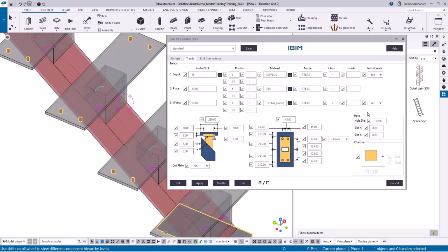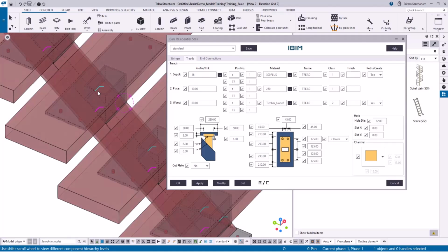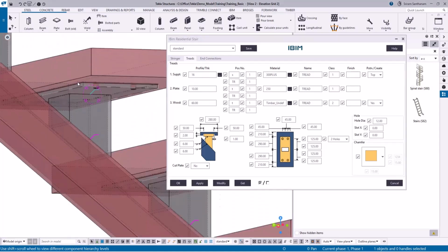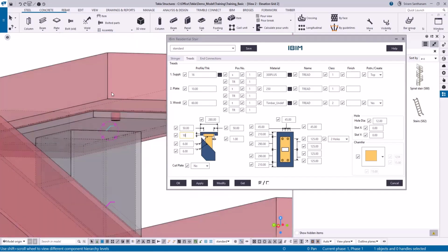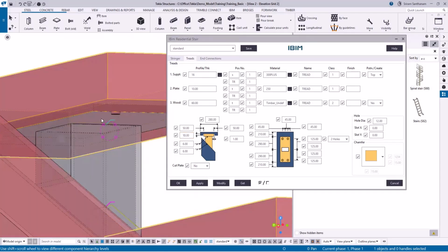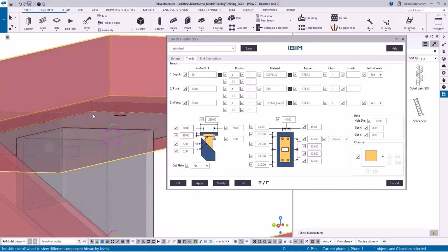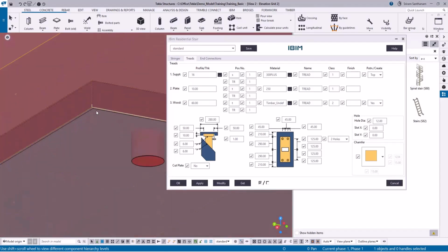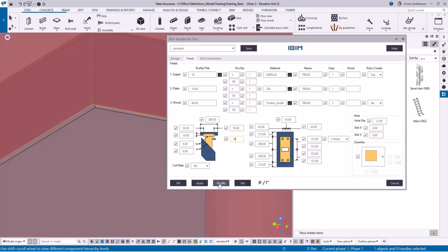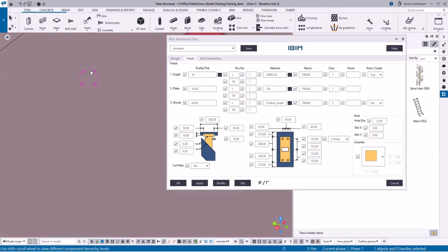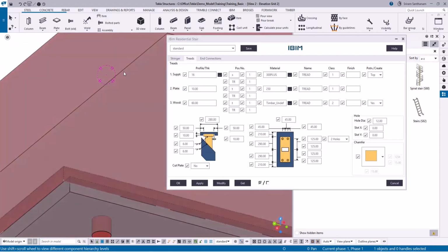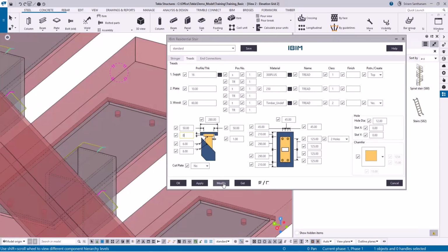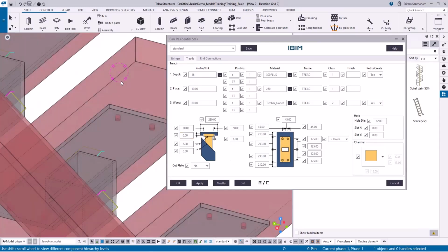For example, let me just change this option to yes and click modify. So now you can see here, let me change this to 10 because the plate thickness is 10. And this is the minimum offset for the cut. Just for the demo, let me type 10 here. Now you can see this gap. So let me just make this option 0 to place the timber on top of the plate.